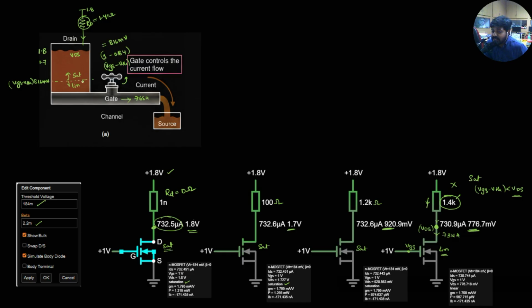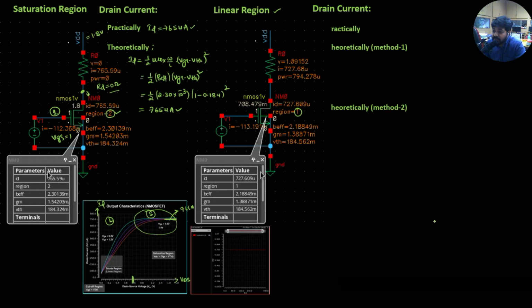Once the water tank is empty, the outlet is open for flowing, but the controlling current will not be conducted. The problem we face is that the transistor goes into the linear region when the current is not sufficiently conducted, because the biasing circuit is not designed to conduct that much current.